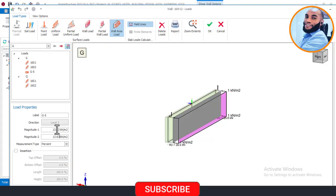Or, in a very smart way, you can use the height of the pool multiplied by the density of water. But basically, we factored many things into consideration, because this is not really an infinity pool, so the water is not full to the brim. We have to remove at least 170 millimeters from the height of the pool, and then we use the remaining 1.3 something meters to calculate the load. Okay, and that was how we arrived at this 13.63.